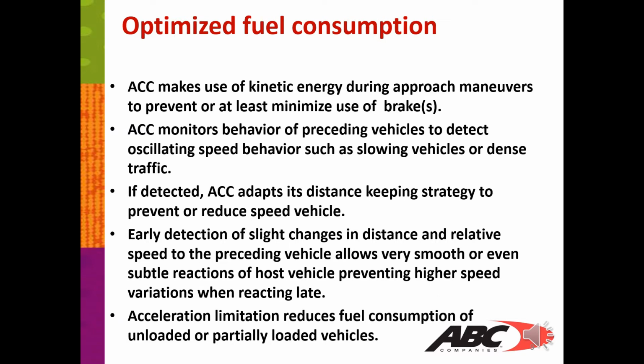ACC makes use of kinetic energy during approach maneuvers to prevent or at least minimize use of brakes. ACC monitors behavior of preceding vehicles to detect oscillating speeds, behaviors such as slowing vehicles or dense traffic. If detected, ACC adapts its distance-keeping strategy to prevent or reduce speed variations.